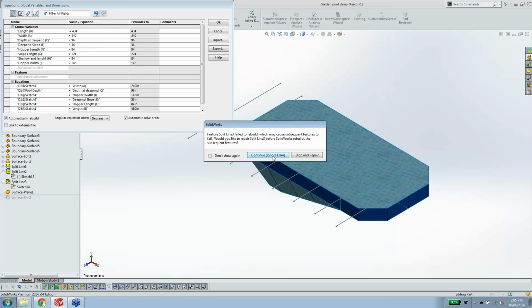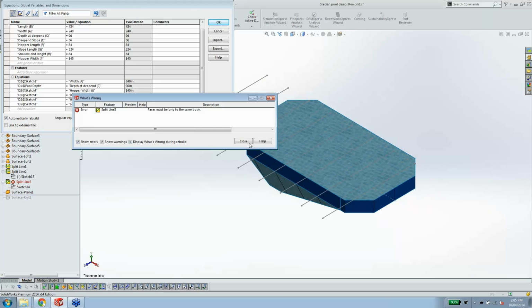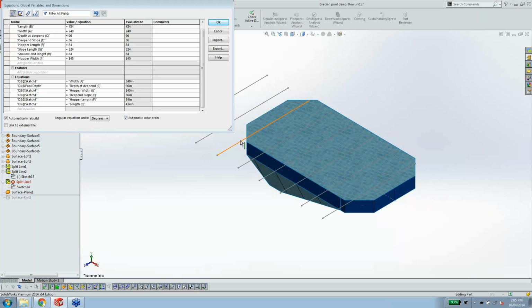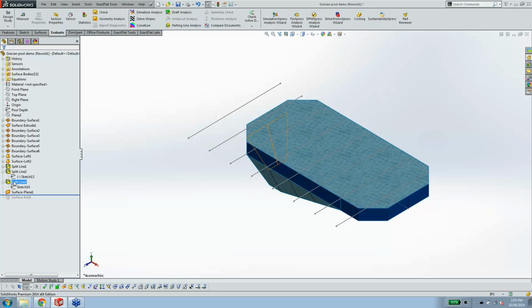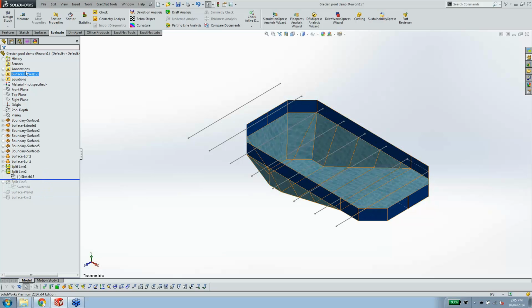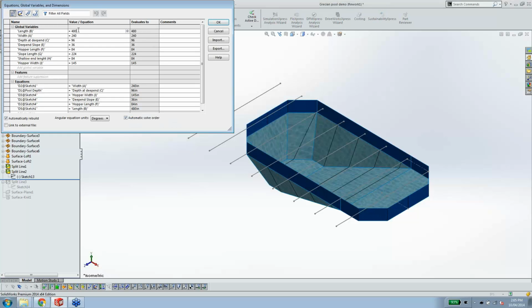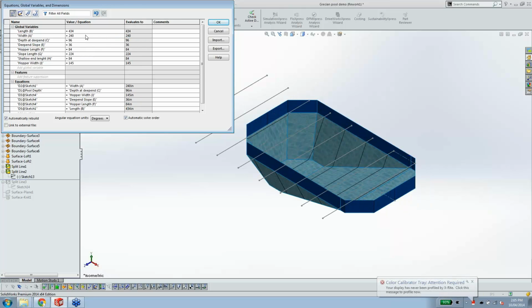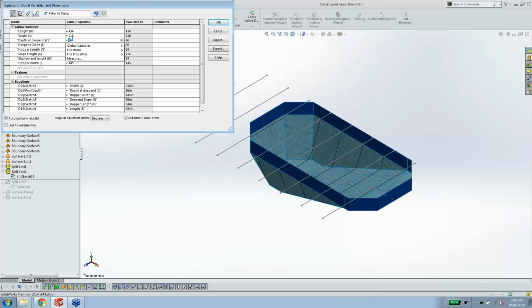But once the model is created, you don't have to really know the modeling process. You can just dimension your pool. And so you can see we've got a little form here. While this pool itself is a 20-foot by 40-foot pool, we're going to go ahead and change the dimensions here by just literally typing in values. So we could change this to 434, which would be a 36-foot. We'll change this one here, this 240 to say 216, which will be an 18-foot, and we'll change the depth of the hopper from, say, 8 feet, which is 96 inches, to, say, for example, 84 inches, which would be 7 feet. And you can see the dimensions are changing as we make that update.